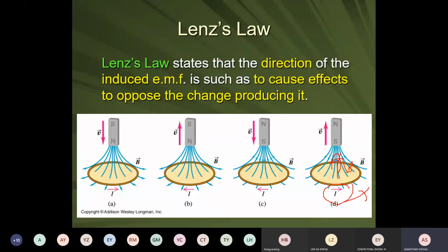Okay. So in other words, in Lenz's law, the current induced here is like inertia. Inertia, you know, right? Inertia opposes the change of state of motion. You don't like any change to your movement. It doesn't mean you don't like movement, you don't like changes in the movement. You can keep on moving, but if you stop, inertia is going to act on you. Or if you are stationary and you start to move, inertia is going to stop you from moving. The same idea here. The induced current opposes the change. The type of change that happens here is the flux change.